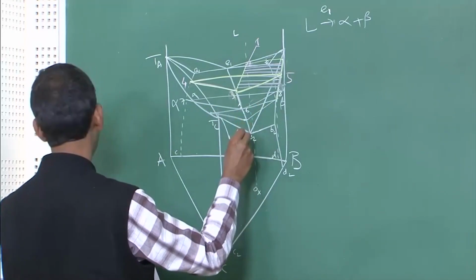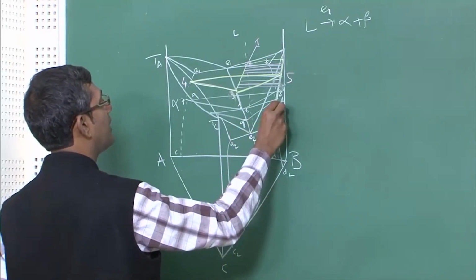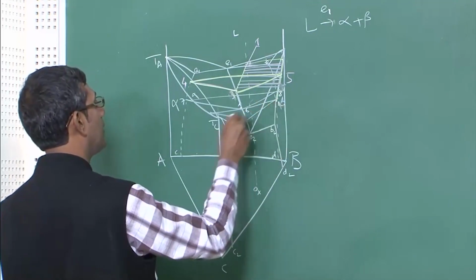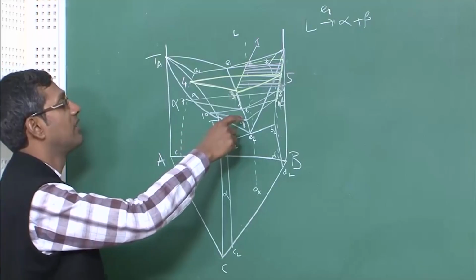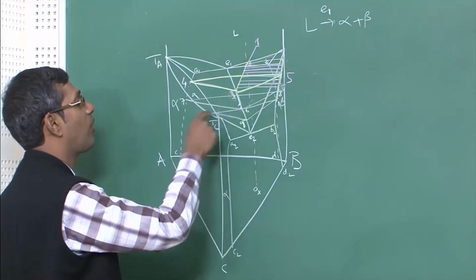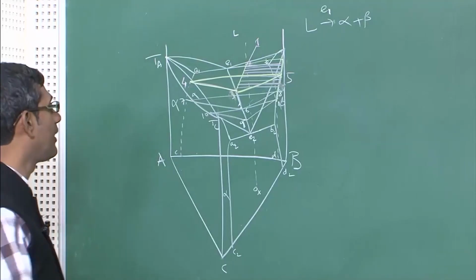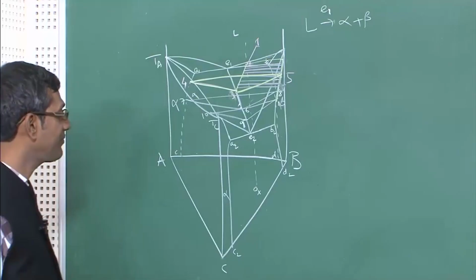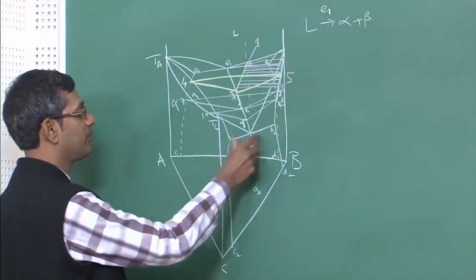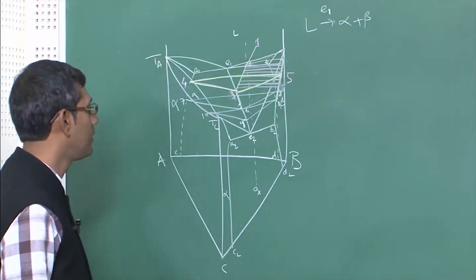You might be wondering how I am drawing these triangles. These triangles are drawn basically connecting points on the solidus surface and the liquidus surface here, and these two are the solid compositions alpha and beta. So, that is how the solidification will continue, and it will get over whenever it hits this alpha beta plateau here between these, which I have shown you last class, solidification will get over.